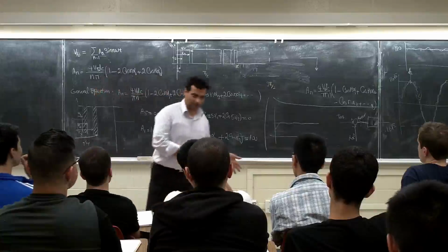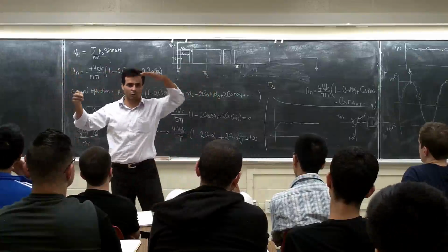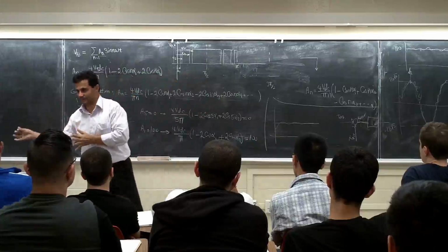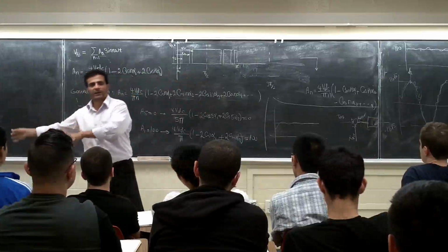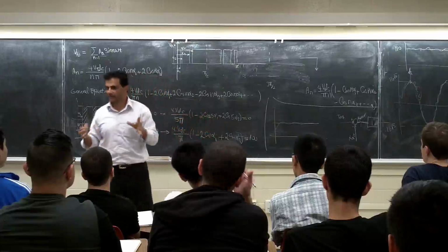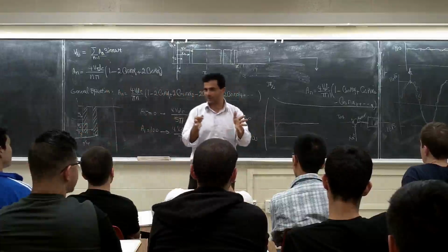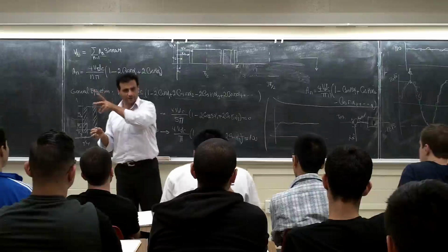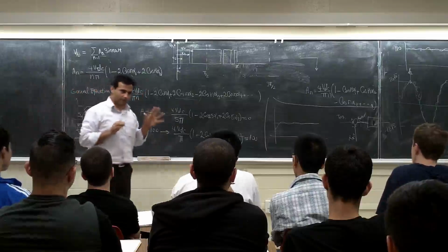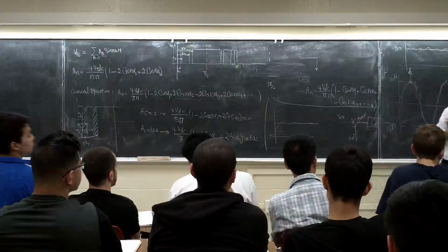Because you are sitting on the same frequency, you know what I'm saying? So you don't have to worry about it. Hey, I'm going to control this peak. If I control this peak, the frequency is already controlled because I'm moving with that system. So this is what we are doing. We are going to take everything to the 60 Hertz system or 50 Hertz system. They call it the synchronous frame, because it means the two of you are moving with the same speed. My voltage is going fast at 60 Hertz, and I'm moving fast at 60 Hertz, so I'm always going to see the same voltage. So reference frame theory is very important, because I know last year I found lots of people didn't understand what they were doing.